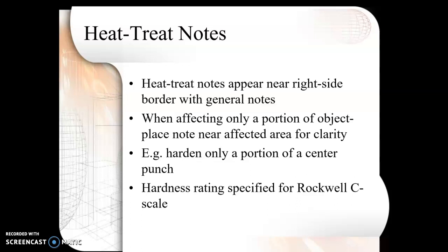So an example of that would be a Rockwell number. A Rockwell number is information related to the hardness of the metal used to make a part. So if you are looking at a print of a technical drawing and you're asked what its hardness is, what you may be looking for is some information on the drawing somewhere that indicates what the Rockwell number is.